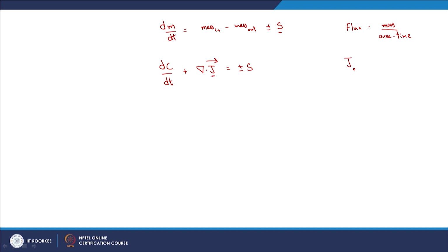So again, this is the flux. Flux can be due to advection, flux can be due to diffusion or dispersion in the context of groundwater, right. Again, advection, what do I mean by advection? If there is a net flow of fluid in one particular direction and the contaminant is then transported by that fluid, I would call that particular kind of transport advection. Diffusion is typically driven by the concentration gradient, and it is random, and you have different kinds, as in molecular diffusion.